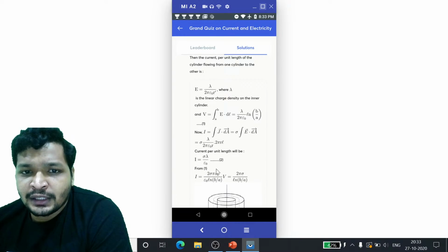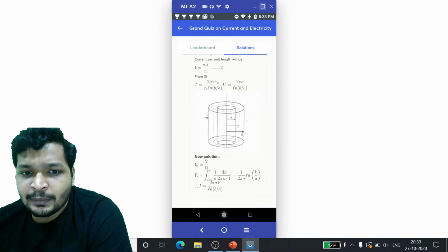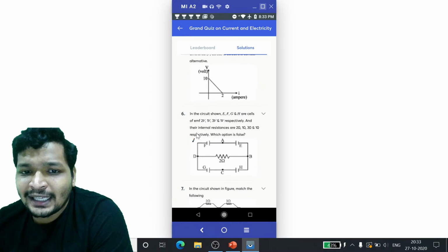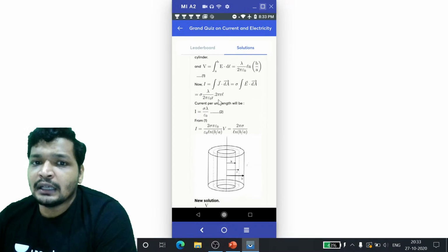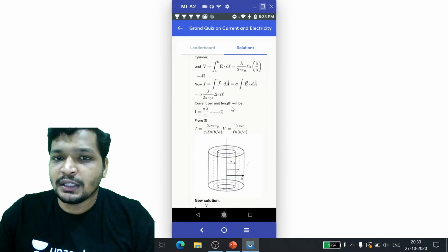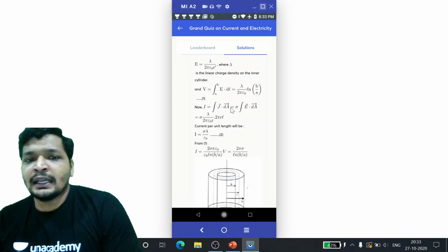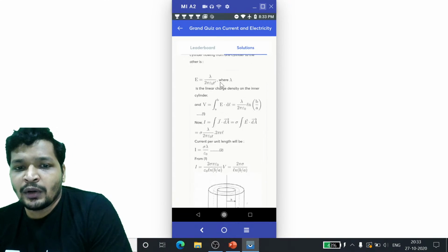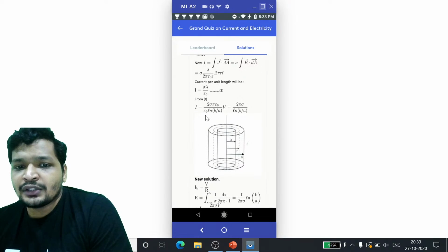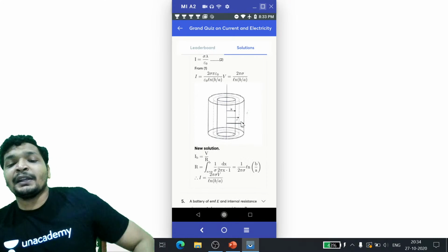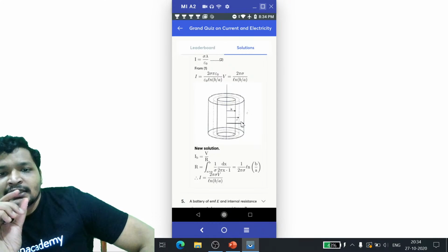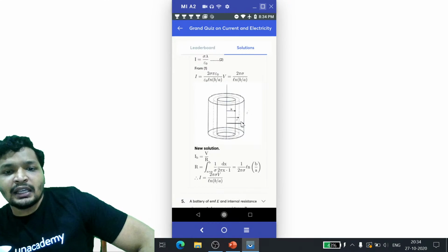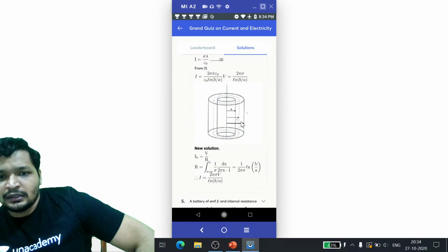So yes, if you remember, this will take a little bit of time to solve. So in such cases, do remember when I was talking about the coaxial cable and the current flowing through it, even in your exam there were 4 options, and in only 2 of them log was there. You have even integrated it and quickly done it, but one of the simplest ways is to assume some dx length, and area is varying all the time. So you'll say rho into L by A. dx is the length through which it has traveled. What is the area? Area is going to be 2 pi r.